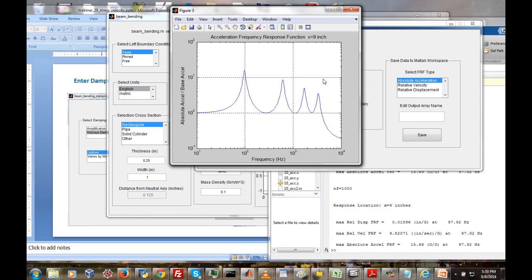Now, a characteristic of each of these four modes is that they all have a Q value of 10, because that's what we specified. But if you try and pick off the peak transmissibility at resonance, none of those modes has a peak at 10. This one here has its peak of about, I like to round off a bit, so I'm going to call it 16. This one's about 9. It's about 5. This is about 3.4. But what we could do is the half-power bandwidth method.